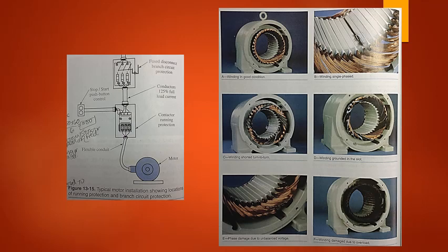Mechanical overload. Another cause of motor failure in small AC motors is mechanical overload. An example of mechanical overload is when a power tool is used continuously under severe mechanical conditions. The tool heats up until the temperature exceeds the temperature rating of the stator's insulation. Once this occurs, the windings are irreversibly damaged. The damage can be so severe as to produce a short between the windings or to the iron laminations.